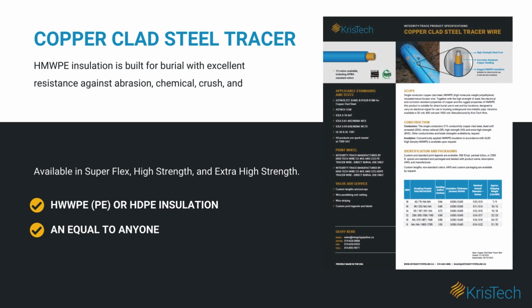Copper-clad steel tracer wire is corrosion resistant, moisture resistant, break load, abrasion resistant, chemical and oil resistant, as well as impact resistant. The difference between copper-clad steel and copper tracer wire is copper-clad steel has a much higher break load compared to the softer metal of copper.